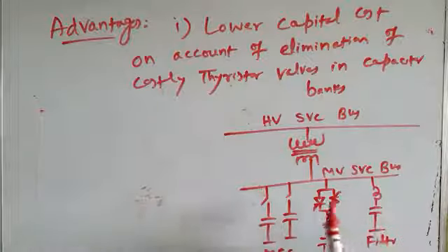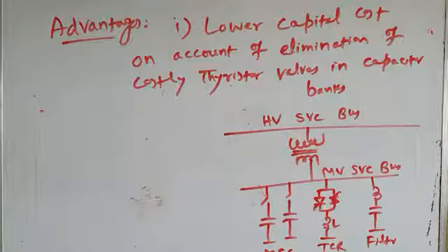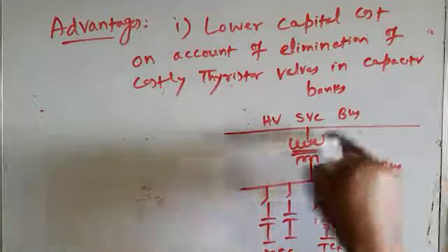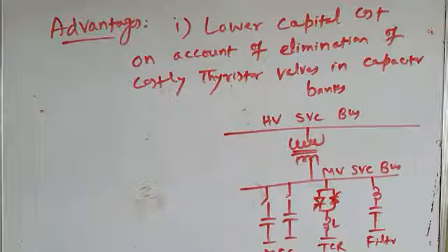And then these two balance the reactive power supply on the bus, and hence they maintain the bus voltage nearly constant. They provide bus voltage support, improve the voltage stability of the system, improve the transient stability of the system, quickly damp the electromechanical oscillations, and also increase the power handling capability, or power transfer capability, of the existing transmission line.